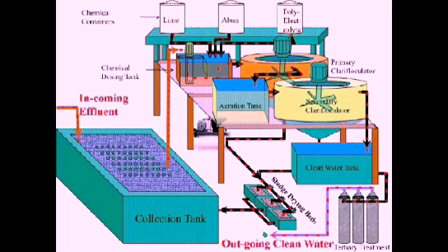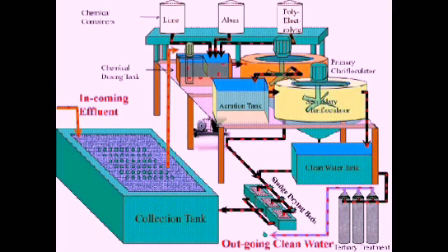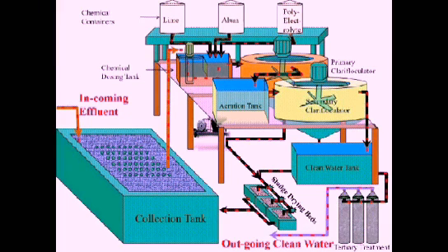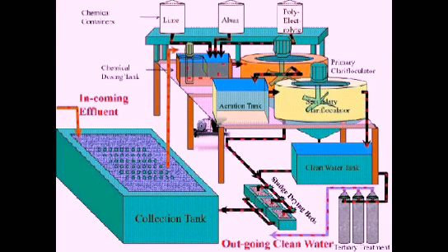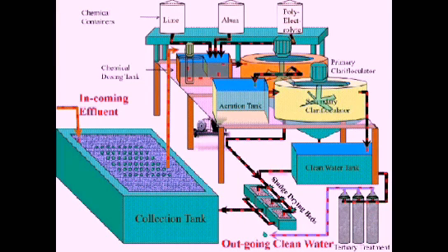In this operation, the decomposed bacteria and other microbiological substances precipitate in the water. This water is then fed into the next stage of treatment, which is the secondary clarificator. In this secondary clarificator, again we have a stirrer, but this one is comparatively very slow since there is lesser sludge in the water now.